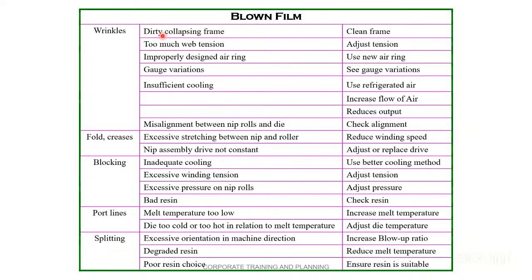Any question here, friend, about the wrinkle? Now, misalignment between the nip rolls and the die also creates wrinkles on the film. Therefore, check this alignment of nip rolls and the die.